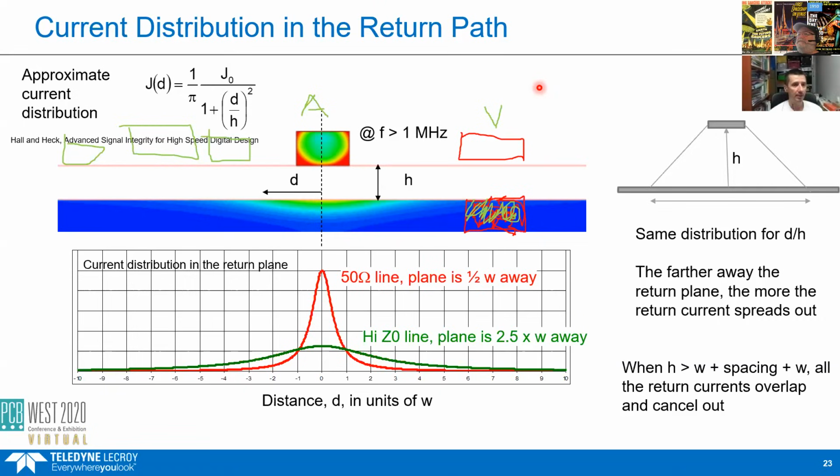But I was actually very surprised when I was doing some simulations, or when I read some articles, there are situations where you can get the full crosstalk, even in 5 millimeters. I don't know how much is it in mils. 5 millimeters is about 200 mils. Yeah, so even for very small lengths, you route two tracks together and you get the full crosstalk.